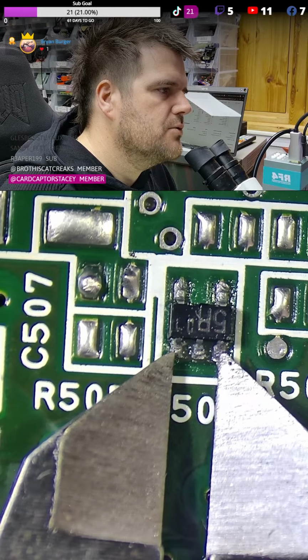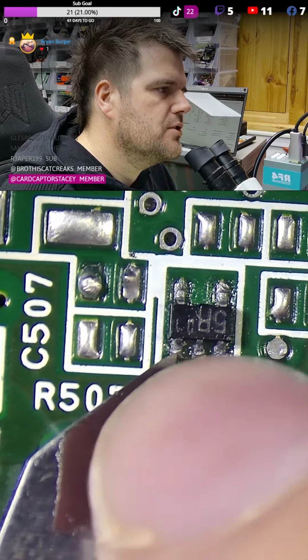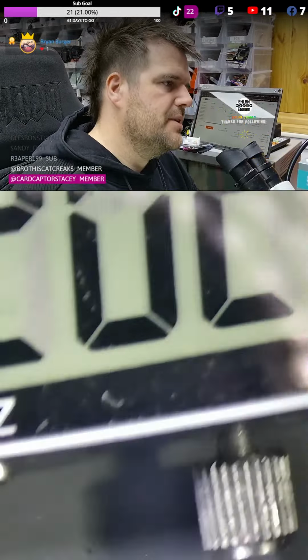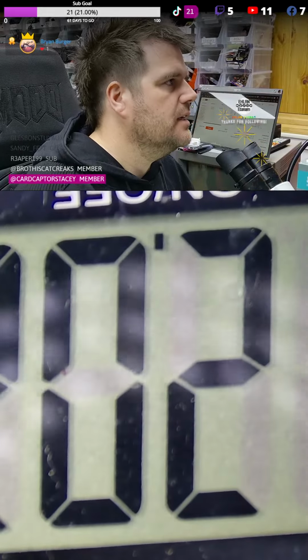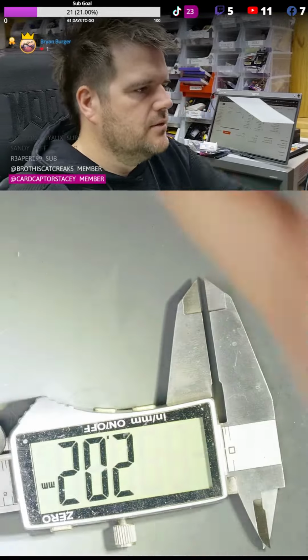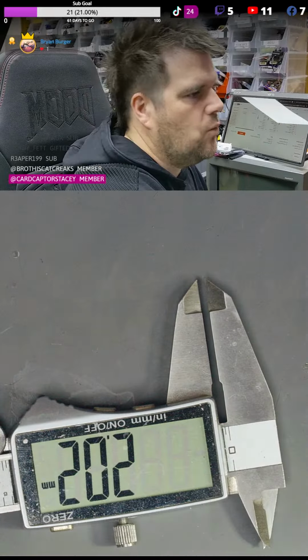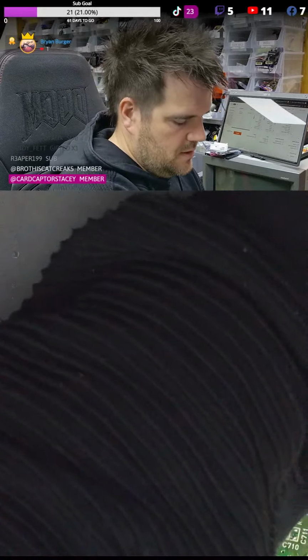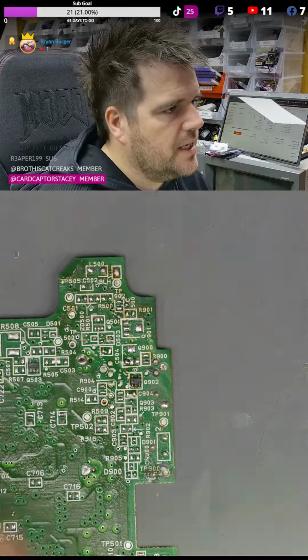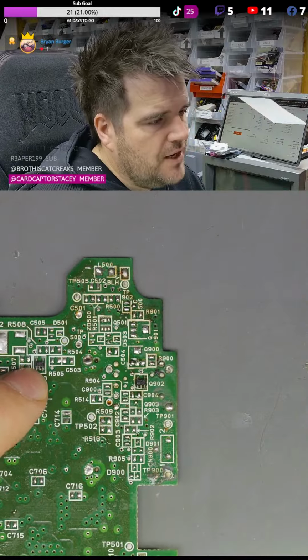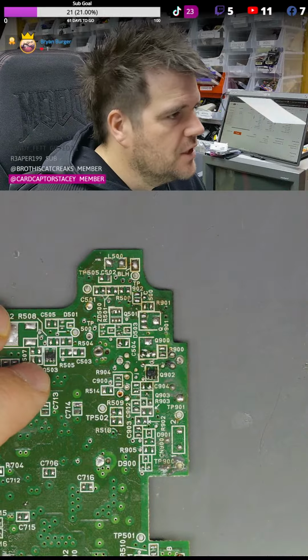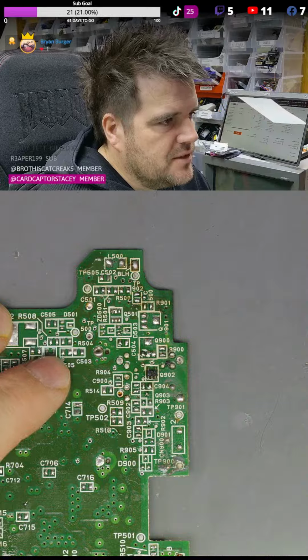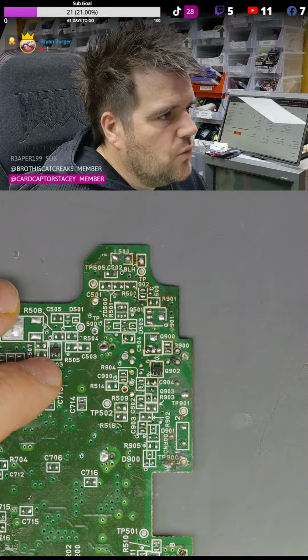And that now means we've got 2 pins in there, 2 gaps, so 1, 2. This means this needs to be divided by 2, and you can see, if we zoom out a little bit, we're exactly 2mm. So that's going to be a 1mm pitch. There's a 1mm gap between the pins. So you have now a package that's got 5 pins. It's clearly a SOT package. It's 5 pins, and we've got a pitch of 1mm.